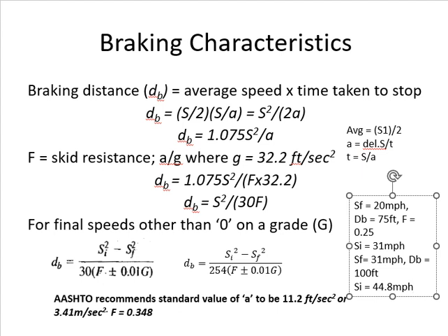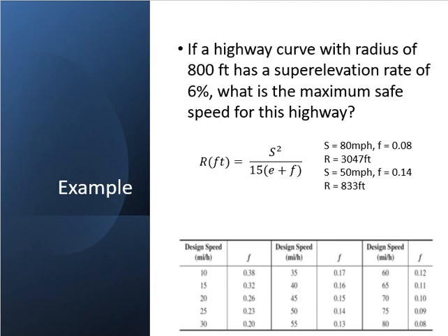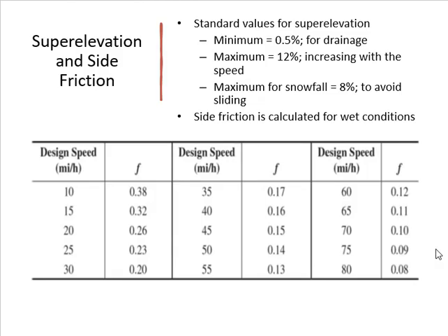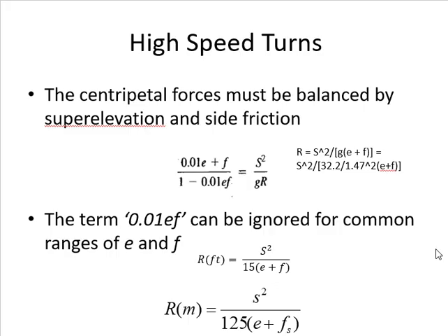Okay, any question? Like I said, we did it in this way because there are two different surfaces. Same surface, 175 distance and so on. Now, one thing to be careful about, I use F here, which is capital F, which we call skid resistance. And what are we calculating? Braking distance. I had another F here, which is the coefficient of side friction. And what am I calculating here? Radius. There are two different values, two different equations. Don't mix them. Clear? Thank you.